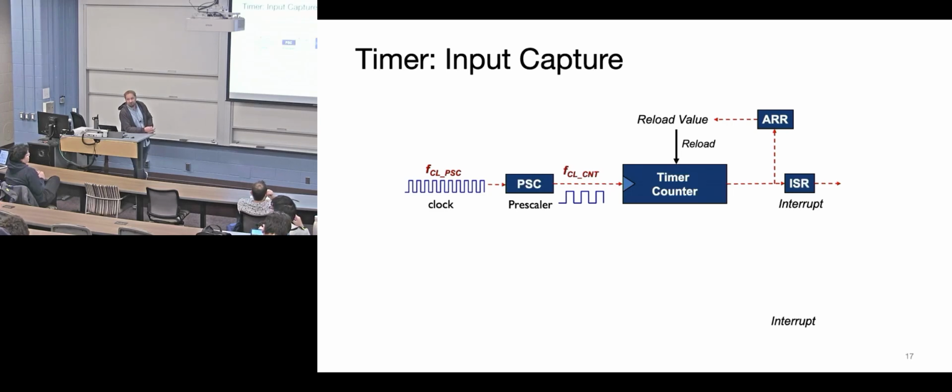It slows down time, so you can count out longer periods of time with the same single counter. Why don't we just have a fixed one that goes really, really slow then? You can't do things fast. You want fast and slow, okay, yeah. More configurable, so you can make this trade-off between how long you go and the resolution of measuring the passage of time. So basically controlling the step size. You guys got that?